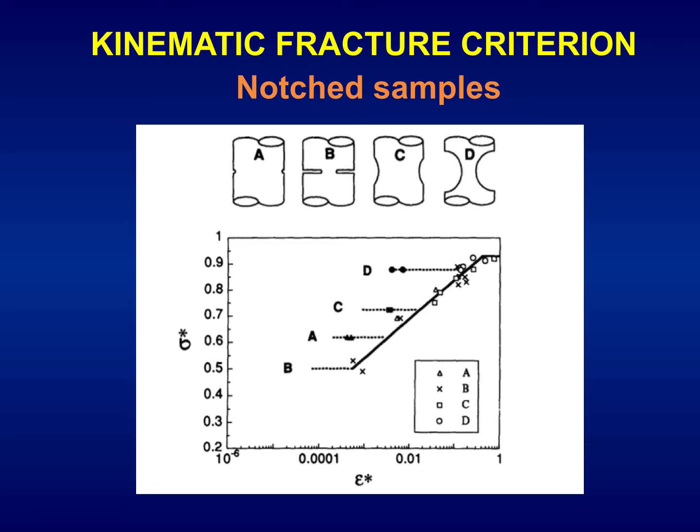In the horizontal axis, we have the average value of the local strain rate at the notch tip or its vicinity. The average value of the notch tip strain rate is a double average, a space and time average of the local strain rate at the notch tip. We take the instantaneous value of the notch tip strain rate and we average it in space and time.